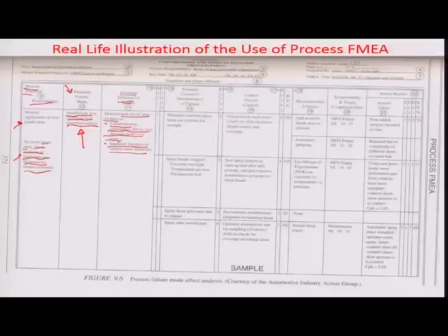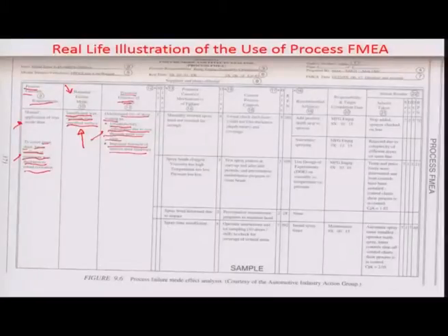Sometimes there is a paint scratch or a paint peel off on the outside, and then if there is a rusted door inner, the rust may always come up on the surface of the automotive, and it may be a very bad look and it may jeopardize the whole painting process. So a layer of paint may get actually peeled off because of such rust coming out, and it may be again another consequence or consequential effect of the failure mode related to insufficient wax coverage.